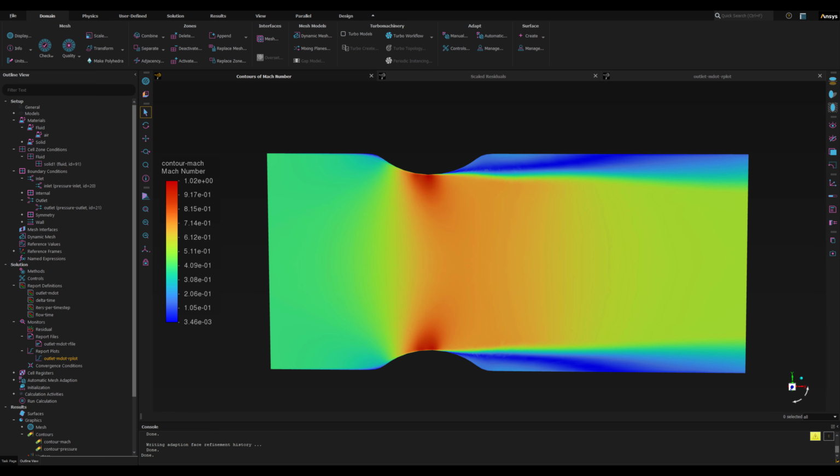OK. Okay, so for this transient, I need to define the time step parameters. The selection of the time step is critical for accurate time-dependent flow prediction. So using a time step of 2.85596 e minus 5 seconds, 100 time steps are required for one pressure cycle. So the pressure cycle begins and ends within the initial pressure at the nozzle exit with this actually setting.